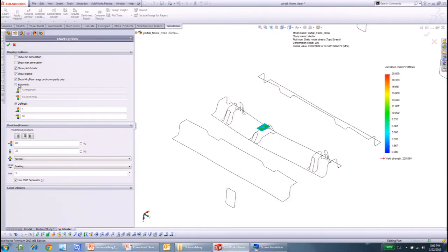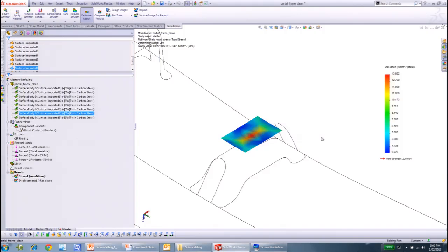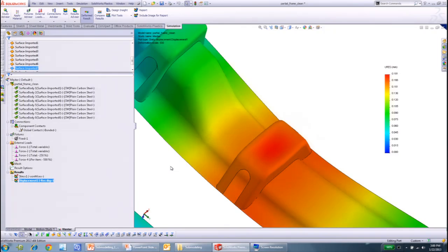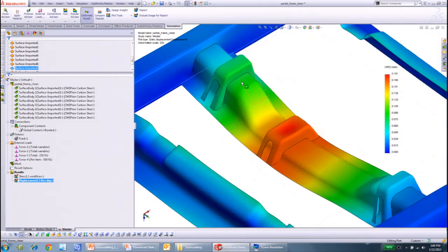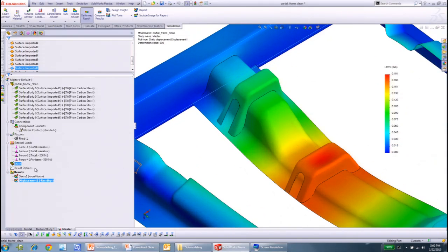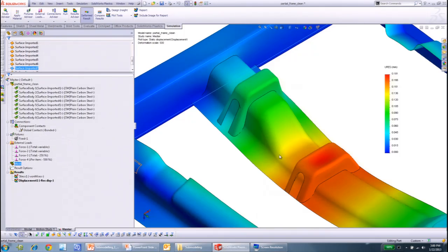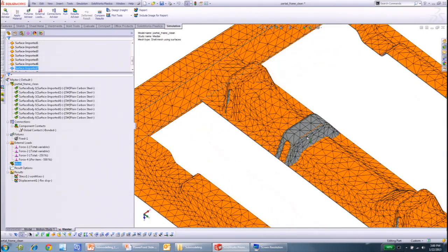So I'm just going to say automatic. It'll try to base it on this, where the high stresses are. So we'll assume that the displacements have converged after the test. I'm going to do a little more detailed analysis. And if you look at the mesh, I wouldn't say quite a fine mesh, it's coarse. But for displacements, I'm okay with this result.